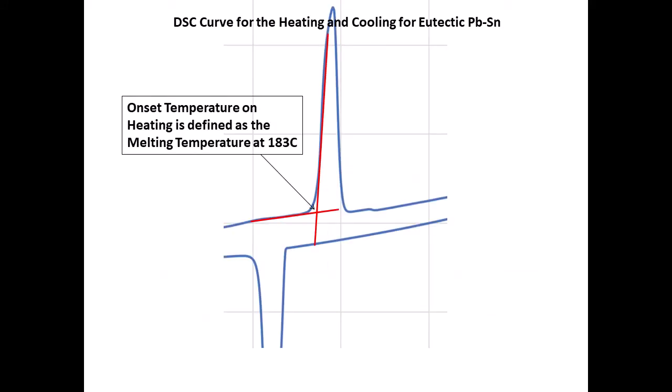It's worth noting that whether the initial liquid is the eutectic composition and upon cooling passes through the eutectic point, or if the composition is to the left or right of the eutectic composition, as the liquid cools through the two-phase region, the liquid composition tracks towards the eutectic composition, and eventually the liquid reaches the eutectic composition and then must undergo the same invariant reaction, transforming from liquid to the two solid phases.